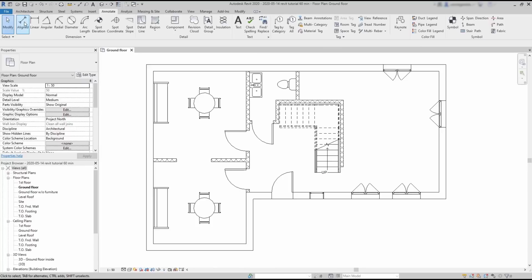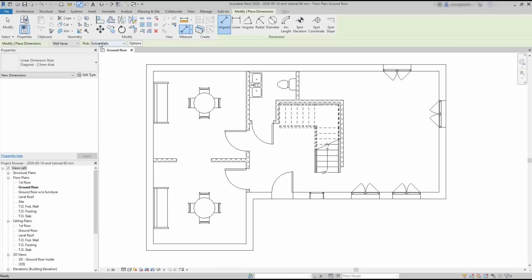In the next example, I'm going to create a dimension line, but this time using individual references. I pick these two reference lines. Then, to place just this dimension, I just click anywhere out of an individual reference. That's what I showed you before. But let's repeat this.